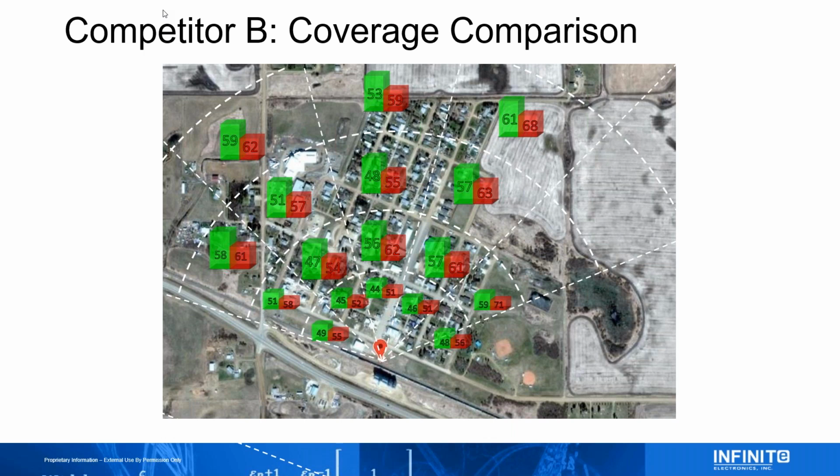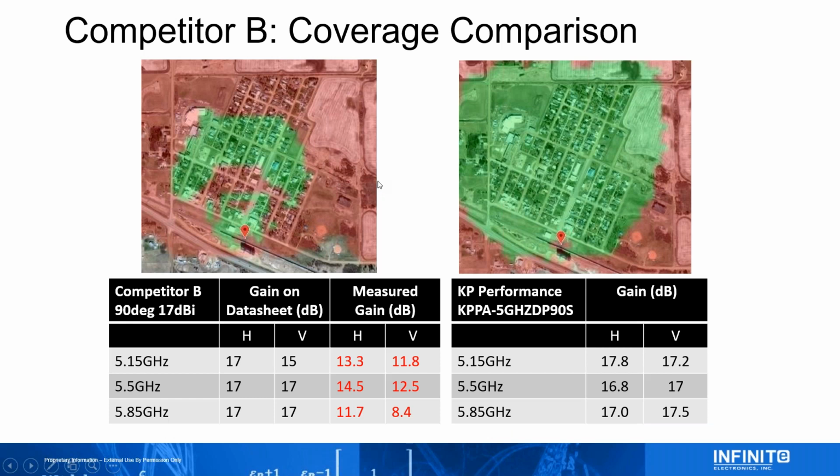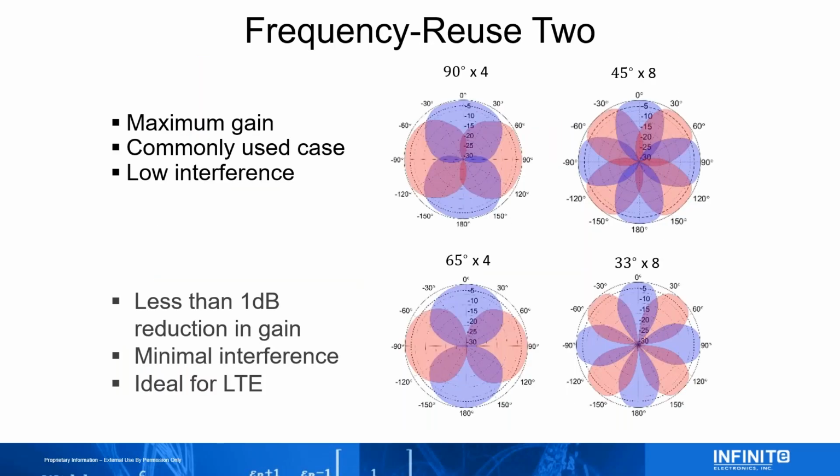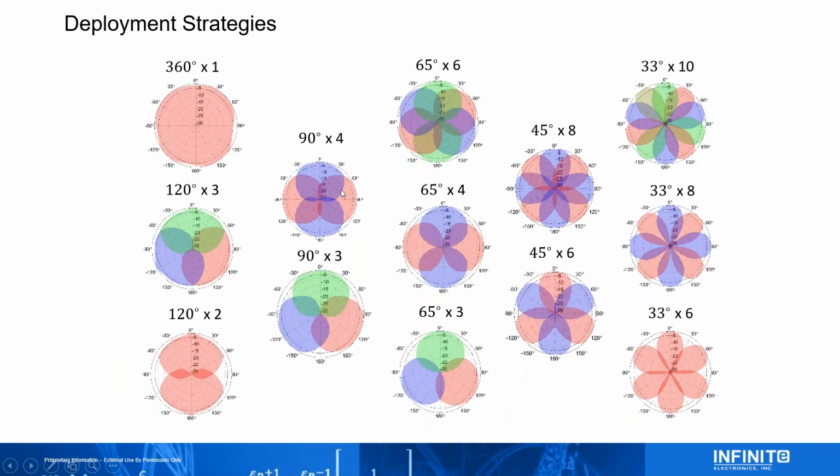I would avoid it as much as you can because you're better off using an equivalent like a microwave backhaul dish, a 1 foot dish, even a flat panel, because you want a nice directive beam. With the sector, if I go back to these plots right here, just look at one of these red circles. You're spreading way too much power out in directions you don't care about. This is point to point, not point to multi-point.